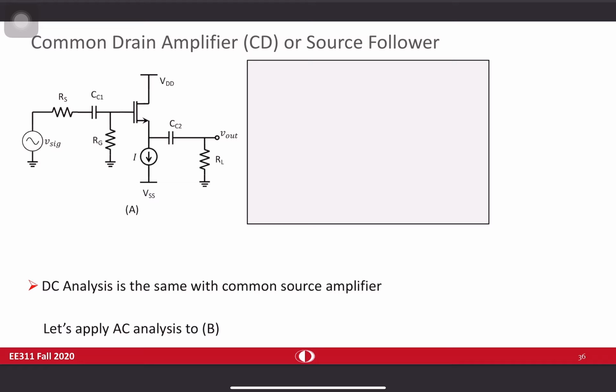But in the previous lectures, I told you that this is not a practical schematic, because in practice you won't have this ideal current source. You have to provide biasing by some other means, and the most common technique is, of course, 4 resistor biasing. So instead of using this schematic, I'm going to draw the same circuit with a more practical representation, where we utilize 4 resistor biasing.